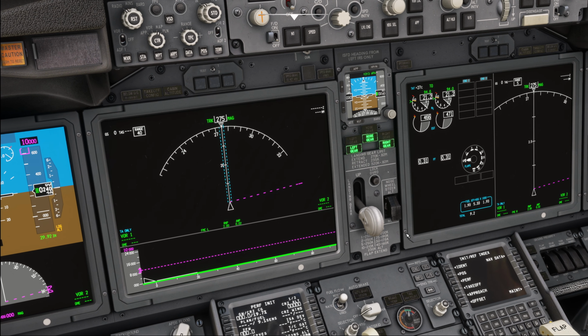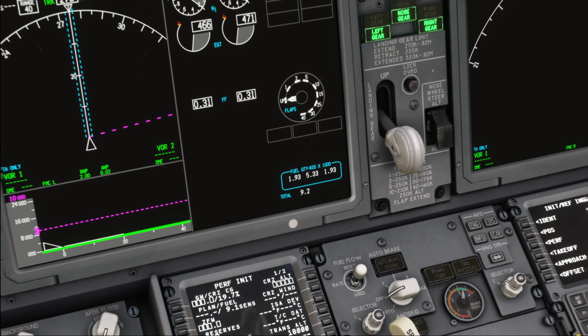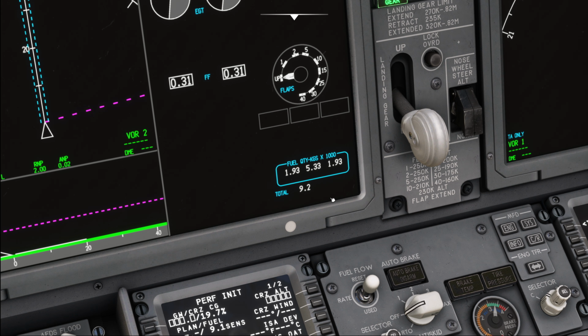The ICAS has also been enhanced with 3 new fuel alerts. Now, the first of them is the fuel disagree alert, and this would show an amber down here next to the fuel gauge. And this basically is a new alert, and it is shown when the fuel quantity is different to what is currently expected.